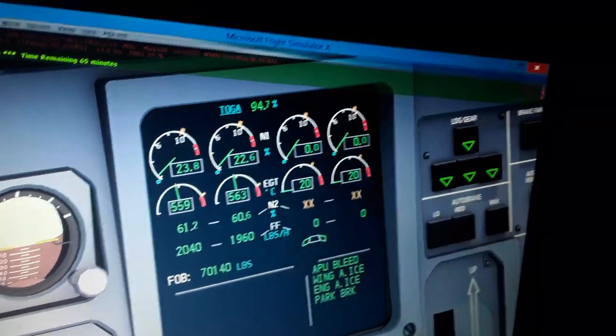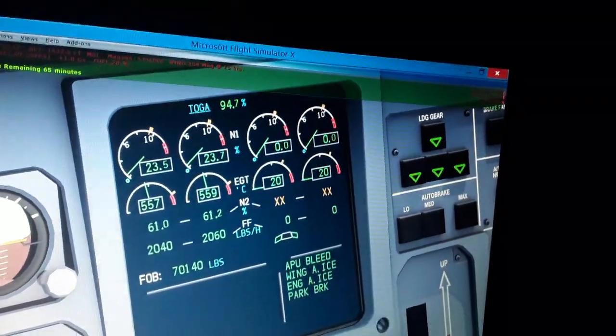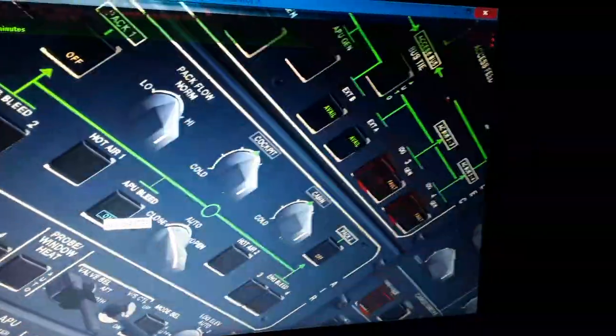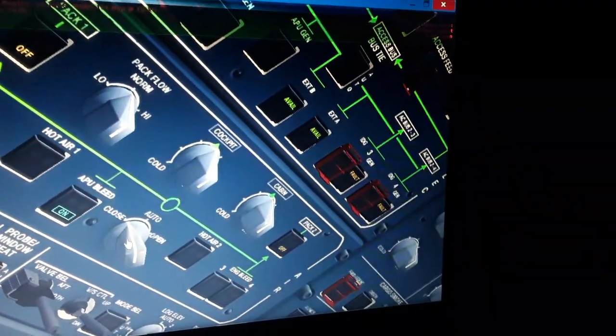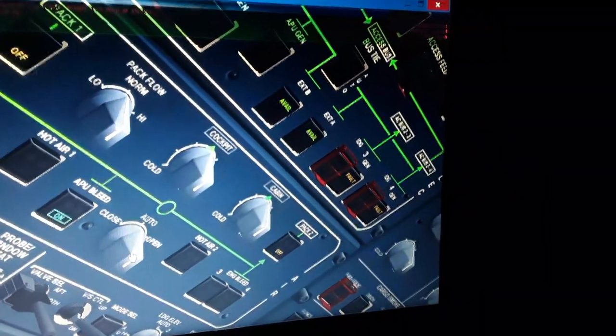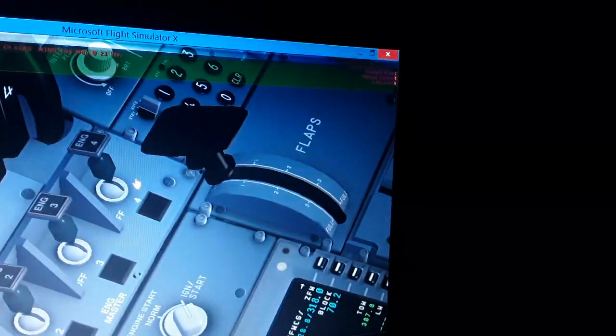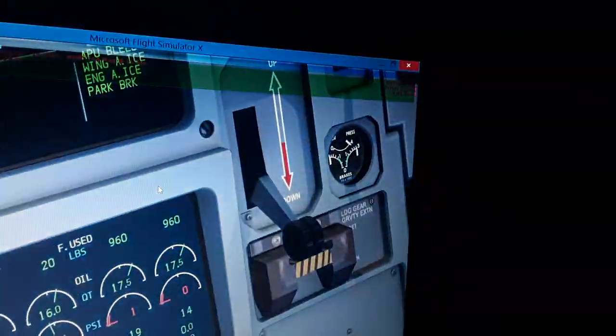The right wing engines are still off, engine 3 and engine 4. So I'm gonna come over here and turn the switch on the other side to the auto position. I can use it in the open, but we need the auto for takeoff. So I'm gonna come and start the right wing engines, engine 3 and engine 4.